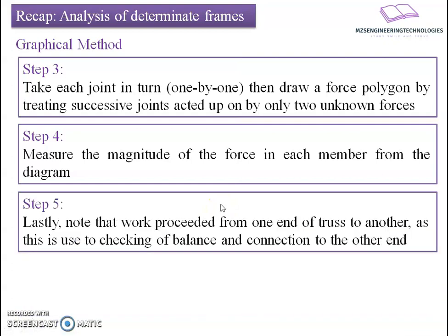And lastly, I will carry out a sequential process in such a way that the end from where I started, I will come back and close at the same end, so as to have a balance or check of the forces in the members with which we started the analysis. With this, we'll move further with a new topic known as the deflection of determinate frames.